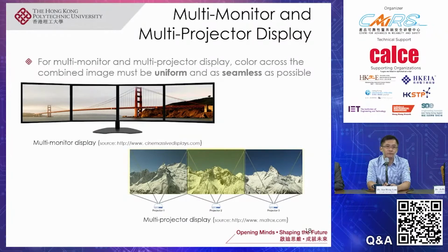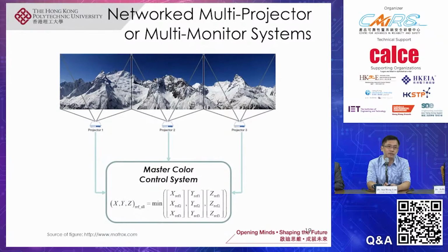So to mitigate this problem, the method that we have proposed can be applied here. If we allow the projectors to communicate with each other, and they always share their tri-stimulus reference values with each other, and always select the minimum set of reference values and use it commonly for all the projectors, then we can ensure that all the projectors will show the same color point, which have the same color performance, despite each of them having a different aging state.